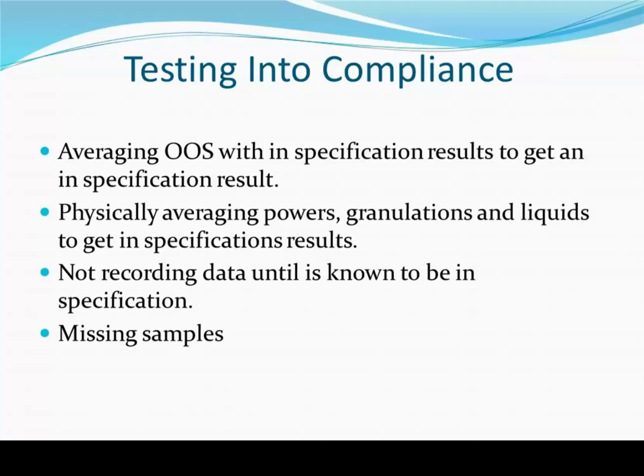That's amazing. What is going on? But when we looked further at it, the analysts that were reading the samples questioned it because they didn't really see the telltale vacuum mark that is usually left on the filter paper when someone is doing a membrane filtration test utilizing a manifold.